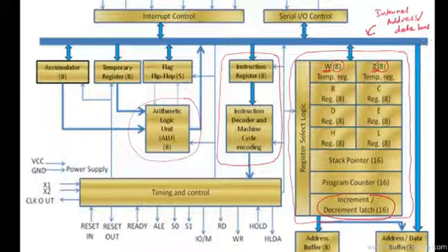So whenever any address or data comes, or rather, let's just refer to it as data, because instructions are data, of course. Whenever the instructions come through this particular internal data bus, at that very moment the instruction register stores this 8-bit data of the instruction, and then it sends it to the decoder, that decodes or understands the meaning of the instruction concerned, and thereby the 8085 would understand what it should do upon a certain instruction.